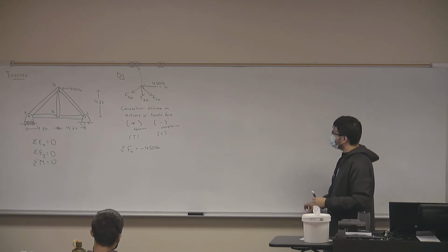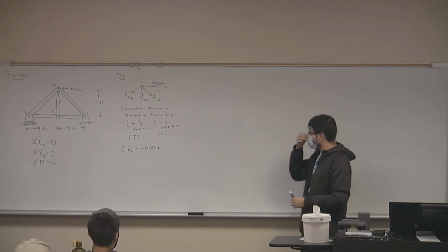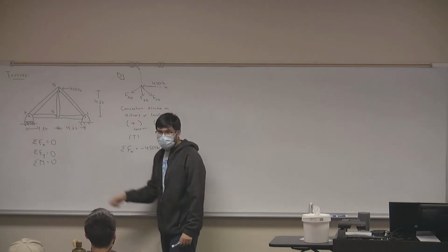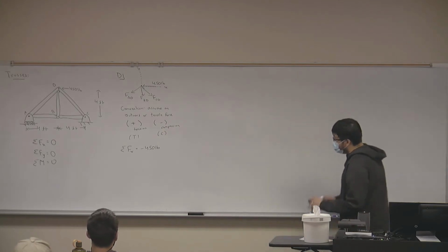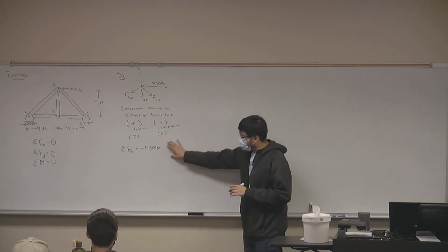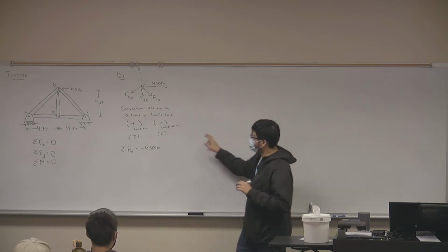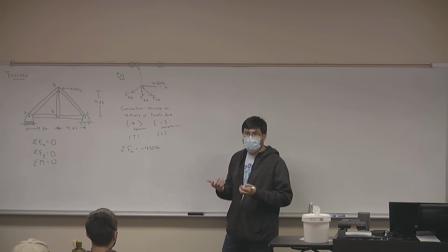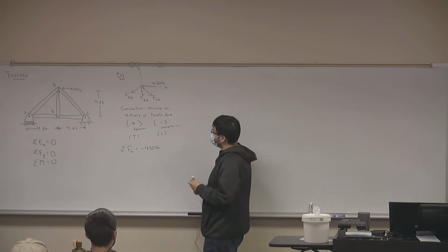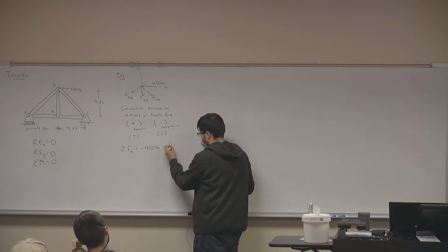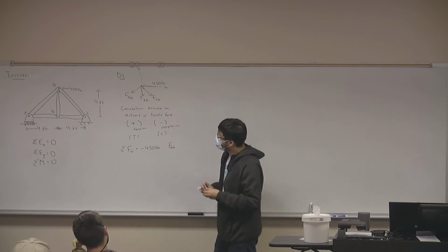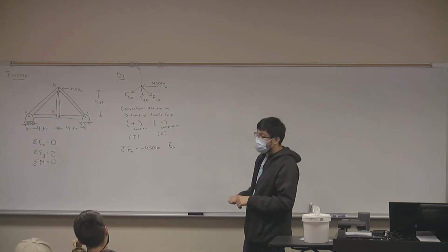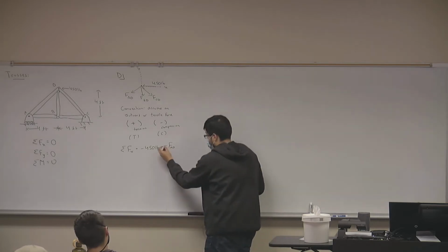We don't know yet because we don't have an angle or a substitute for FAD and FA or FCD. But we can find an angle. So that's why I said we don't know yet. Okay, so let's write these forces as simplified as we can. So let's write everything in terms of one of these 3 forces. So FAD, okay, but in the x direction, what do we have? Force AD cosine 45, that's correct. And that means minus that. That is correct.